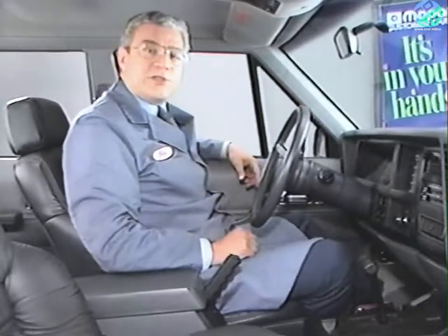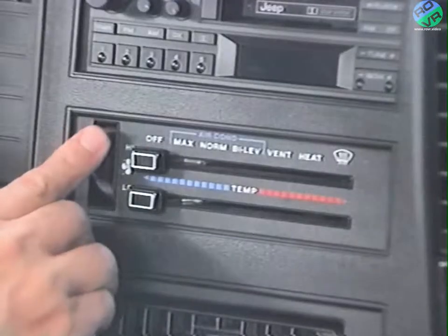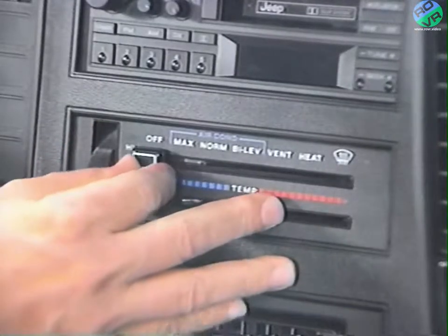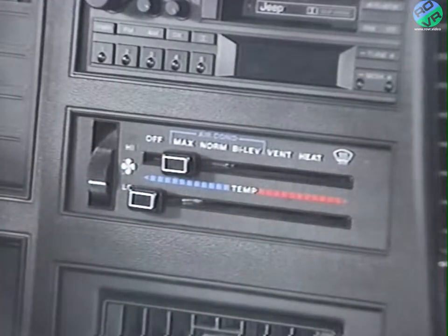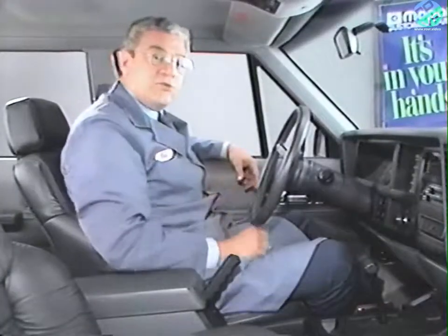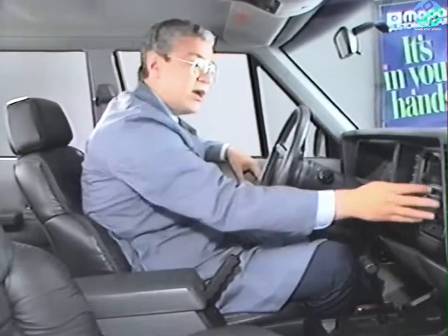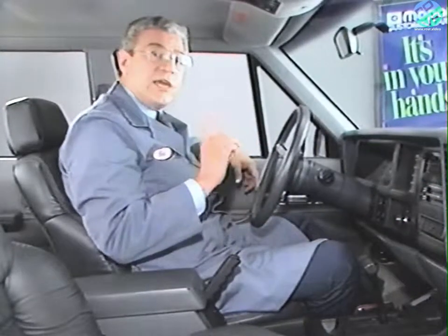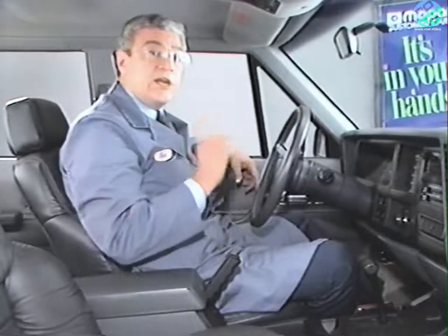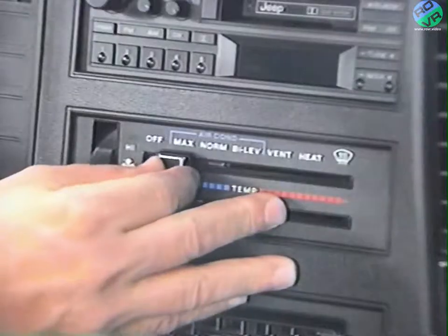When the driver positions the mode lever in the air conditioning position, the engine controller receives an AC select signal. It also receives a request signal from the air conditioning temperature control thermostat. Listen to the engine RPM when I select the air conditioning mode again.